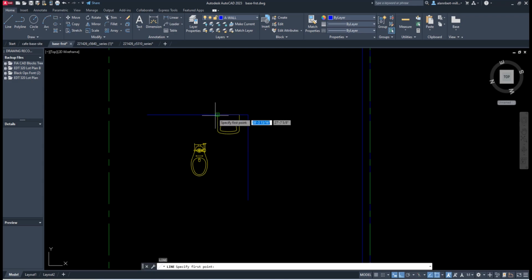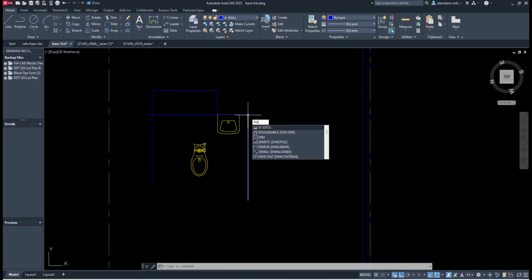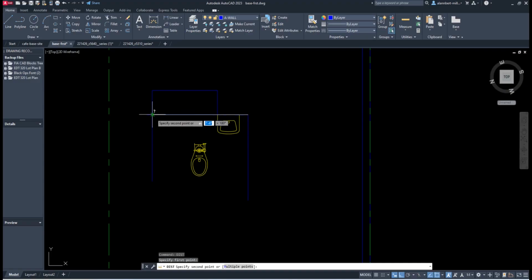So what I'm going to do is I'm going to just draw a line here, and I can even draw a line, 60 inches, 60, enter, and then go down. Okay, so let's now look at the total dimension from this intersection to the endpoint over here. So I'm going to do a distance endpoint to this intersection over here, and that is 7'4".